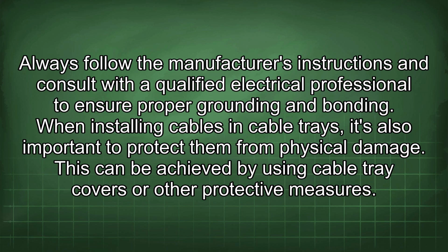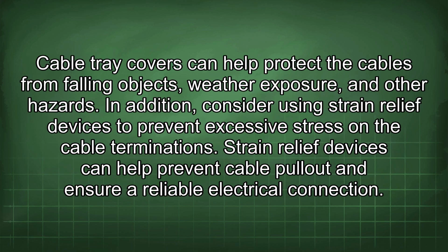When installing cables and cable trays, it's also important to protect them from physical damage. This can be achieved by using cable tray covers or other protective measures. Cable tray covers can help protect the cables from falling objects, weather exposure, and other hazards. In addition, consider using strain relief devices to prevent excessive stress on the cable terminations. Strain relief devices can help prevent cable pullout and ensure a reliable electrical connection.